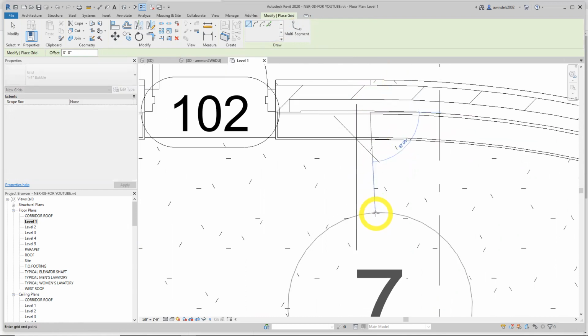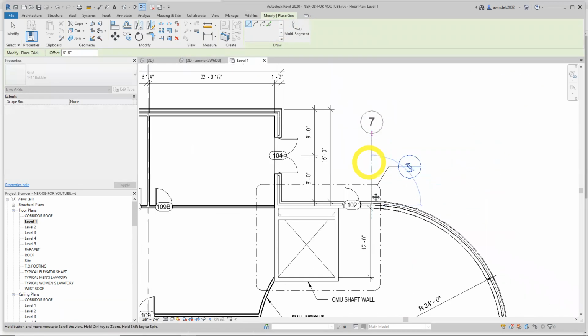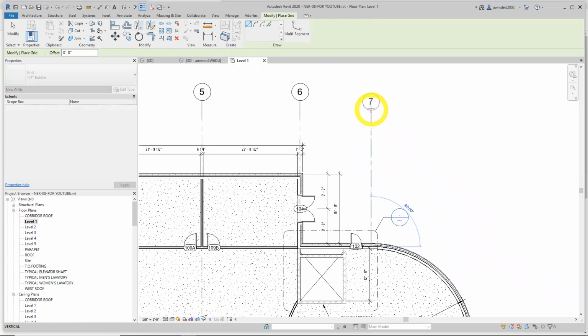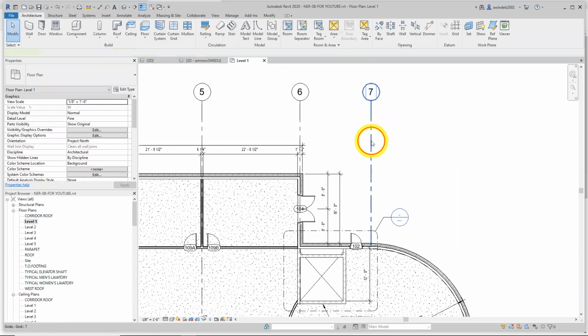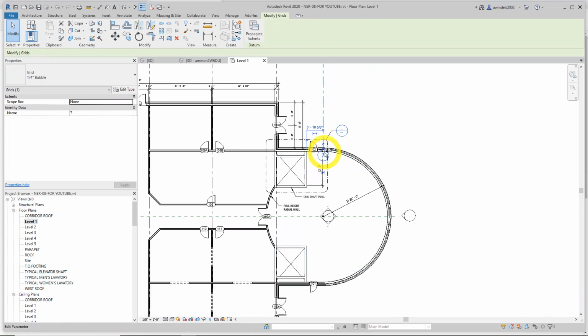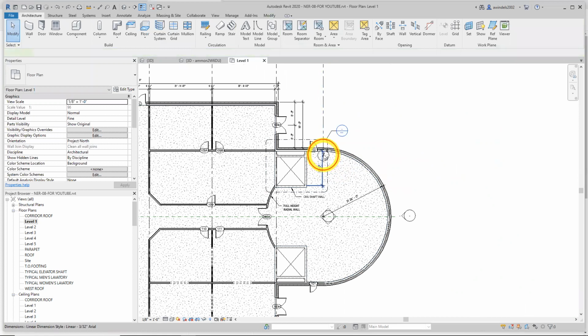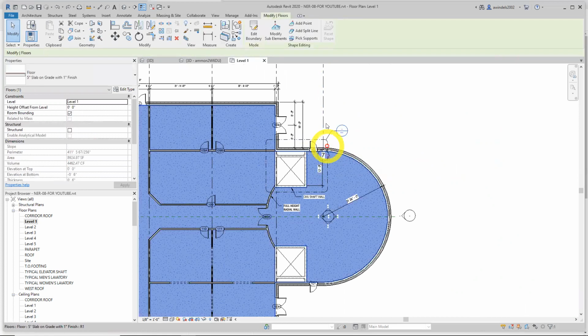Let me bring this point, could even bring it up this way, and I'll use my grips to bring it down to the south later. And if you hover here, they automatically align. Escape twice. Let me turn that grid on. Let me pull the grip here. You can break them as well, which we're going to do later to give them jogs. Escape on that, 2 escapes.